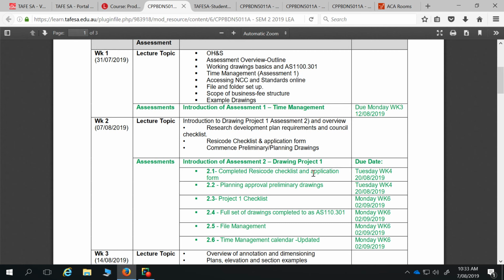Heritage, conservation areas. There's also some sustainability written into most development plans, and some of them have to do with rainwater tanks, which is obviously a part of it, and then bushfire fighting tanks as well, so where are we going to locate those if possible. Sometimes there are height restrictions on rainwater tanks. They might say the tank can't be any higher than 2.4, so you might be thinking you can go slimmer and higher, but you can't, so you've got to go wider, and it sometimes messes up the boundaries, etc.